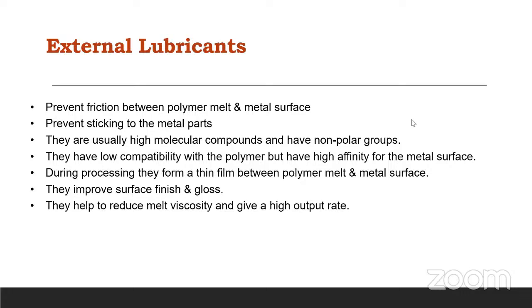I have discussed the requirement of compatibility. Your additive should be compatible with your polymer material. When it is compatible, it blends well and properly disperses within your polymeric matrix. If it is not compatible, it will not blend and it will not give you that additive effect in your polymer.